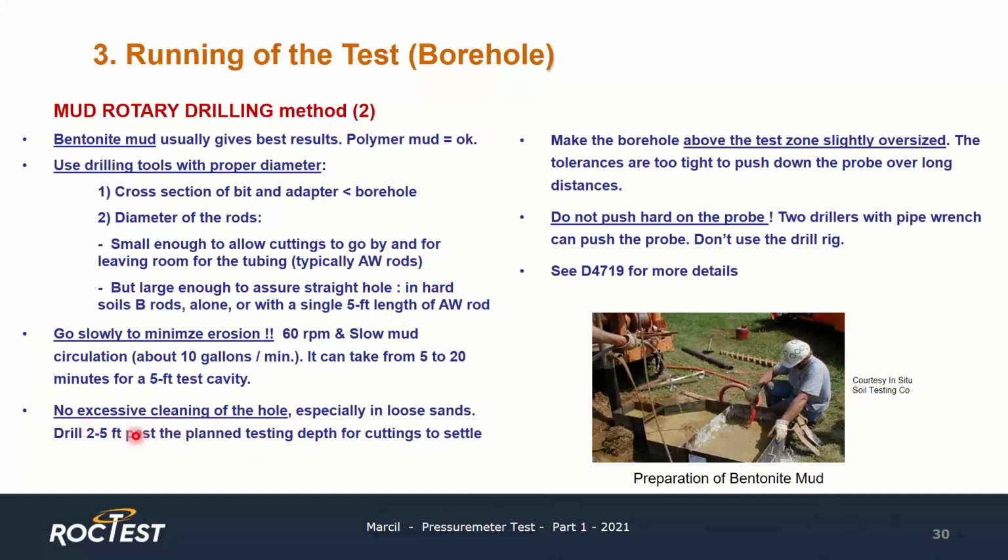Also, you should not perform excessive cleaning of the drill hole, especially in loose sands. If you do so, you may end up with a borehole that has a diameter that is too large. And it's good to have some room under the test depth for the cuttings to settle, if there are any cuttings. Also, it is good to make the borehole above the test zone slightly oversized.